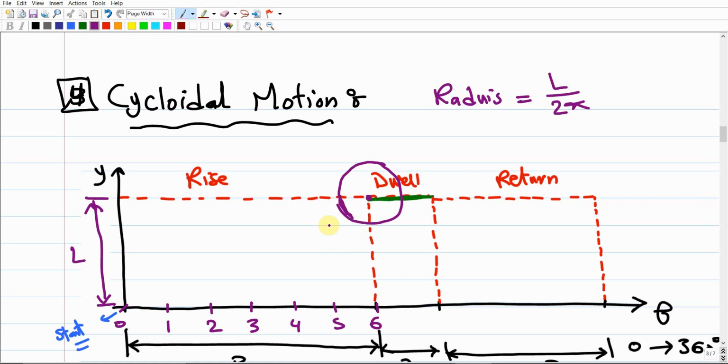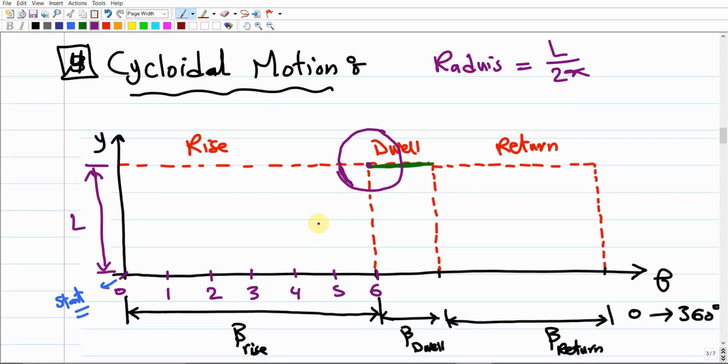Make sense? Then your objective is to break down this circle into 6 segments. The complete circle is 360 degrees divided by 6 segments. This gives us each segment should be 60 degrees. So how can we measure the 60 degrees? Starting from the horizontal axis, this horizontal line, you're going to measure an angle to the top of 60 and another angle down of 60. You're going to use the protractor to measure these angles. Then you're going to mark a point, 60 on the top, 60 down. Then from these points you're going to draw a line and draw another line.